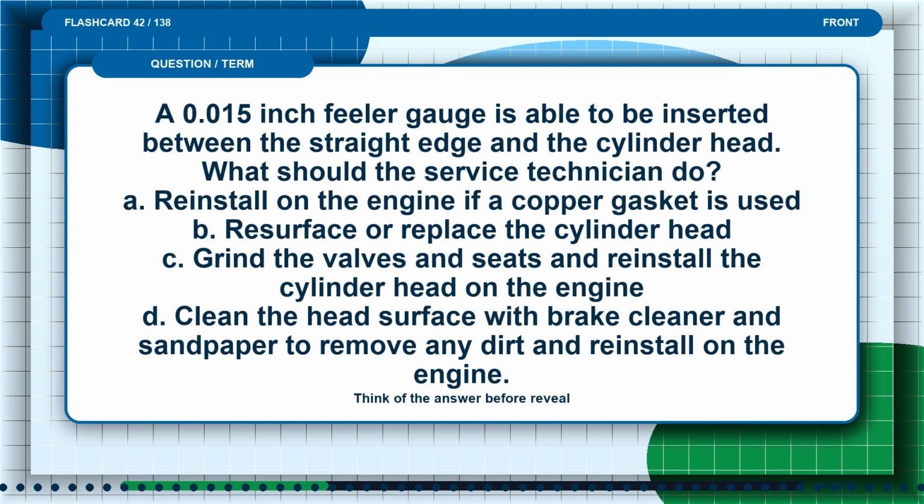Flashcard 42. A 0.015 inch feeler gauge is able to be inserted between the straight edge and the cylinder head. What should the service technician do? A. Reinstall on the engine if a copper gasket is used. B. Resurface or replace the cylinder head. C. Grind the valves and seats and reinstall the cylinder head on the engine. D. Clean the head surface with brake cleaner and sandpaper to remove any dirt and reinstall on the engine. Pause and think of the answer before the reveal.